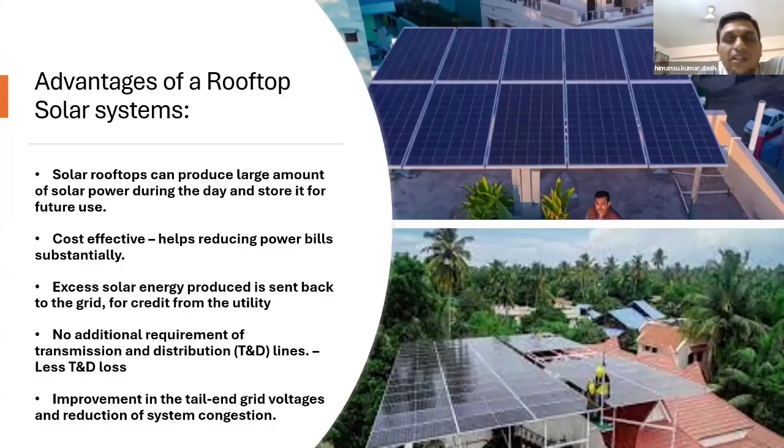That is, we know that suppose we are in a locality where we have say a 1 MVA transformer for our locality. Now what will happen if we go on adding load without adding substantial capacity to the transformer MVA rating? Then ultimately a point comes when the total reactive power demand required by these households cannot be met with this transformer. That is, the MVA rating of the transformer is not sufficient enough to drive the MVA load. So what happens, there is voltage drop.